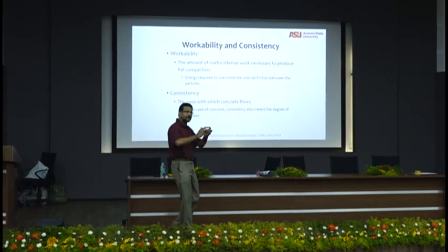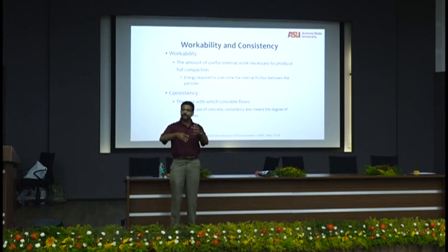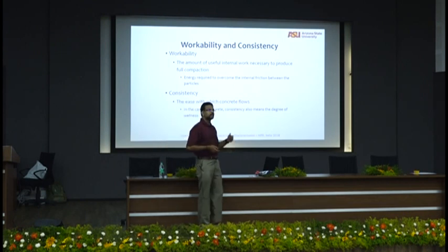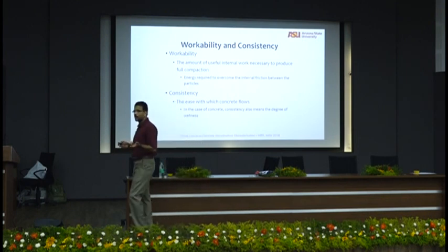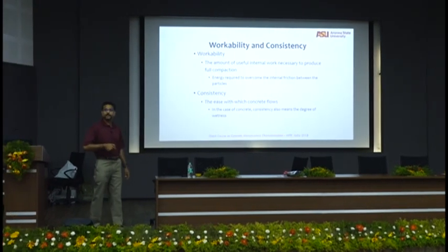Flowing of any particulate media is nothing but overcoming the frictional force between particles. Two aggregates together, very high friction. Put in cement paste as a lubricant between them, friction goes down, right? So basically what you're doing is reducing the friction. So workability is a means in which you figure out how much energy is required to overcome the friction between the particles, and consistency is the ease with which concrete flows.